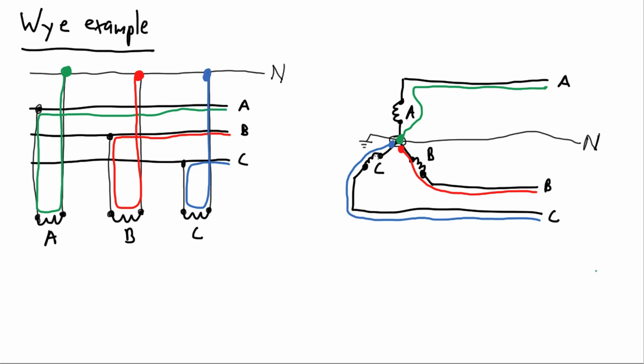And it's completed. What you can see here, a distinguishing characteristic of the Y, is we can't use that yellow tracing like we did in the delta to form that complete circuit. These lines just go out. And so there's another distinguishing characteristic you can see here in the way that it's connected versus the way the delta is connected. So notice now with the neutral connections how we have 3 connections, 3 lines coming in and joining in 1 on the neutral. We'll demonstrate that here with this yellow box shown there. That is this connection here.